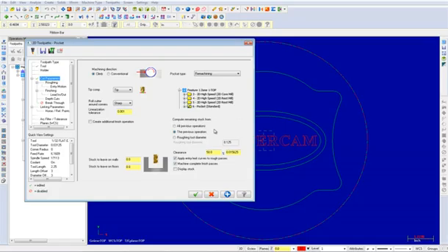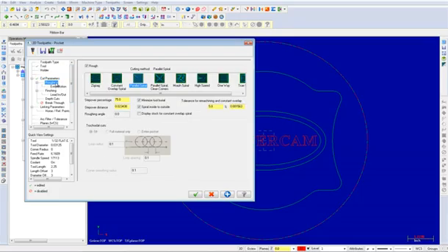Once the parameters have been changed, select the roughing parameters. Ensure that parallel spiral is enabled. Also, change the step over percentage to 55. The rest of your parameters should appear as shown. Finally, enable the option Display Stock for Constant Overlap Spiral. You should note that the cutting method is defined by the pocket type and cannot be modified for remachining.